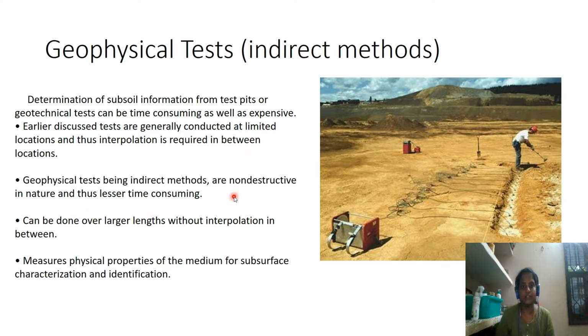We may think it is a hard stratum, but once we do a geophysical test, we will confirm that it could not be a hard stratum really. So this is a supportive test which is done for the test results that we obtain by boring, or it can also be done before starting any boring or test pits.